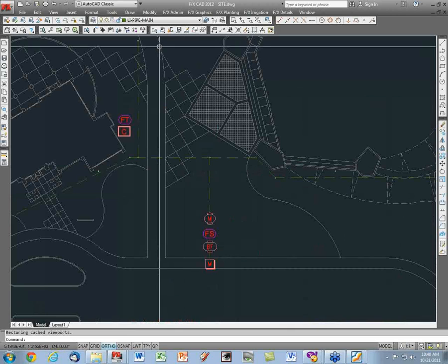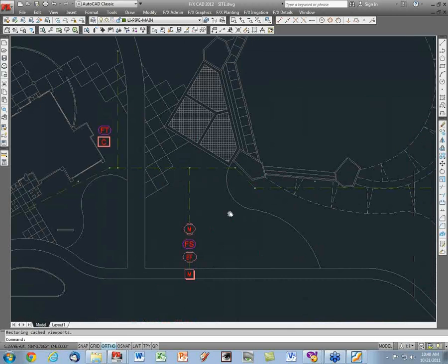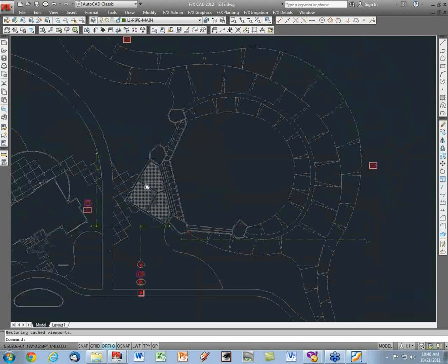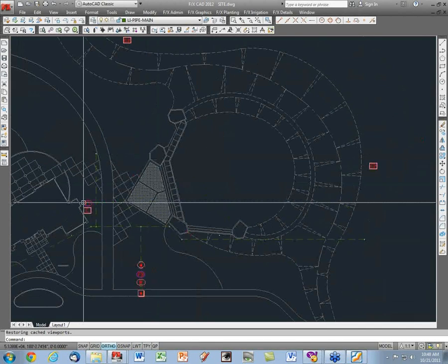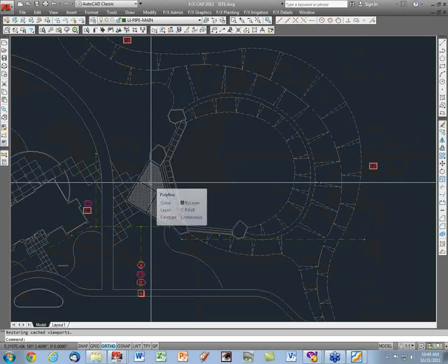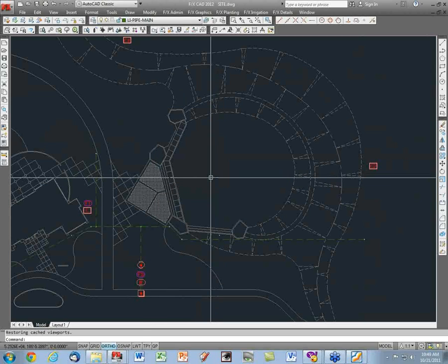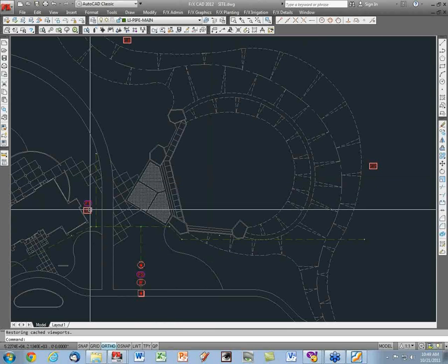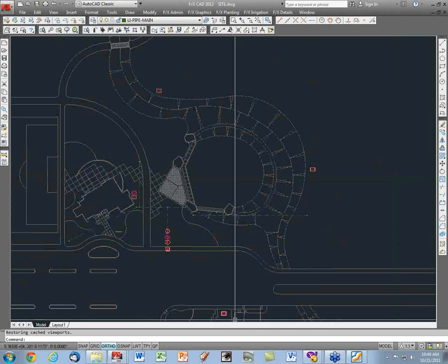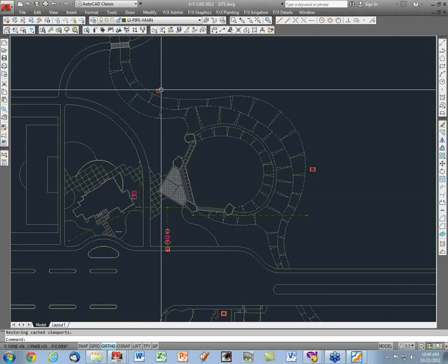And I haven't added yet a detail for this. So you're saying from this flow sensor to this transmitter, I can't go over 2,000 feet, right? Well, we'd like to. That gives you a pretty good distance. If you had to go further than that, we just would suggest that you call us and we talk about maybe increasing the wire size or the power size or something like that. Gotcha. Let's pretend, this is certainly not 2,000 feet. Then from this controller to either each of the others in a spoke or serial, it's still 2,000 feet to there. Is that right?